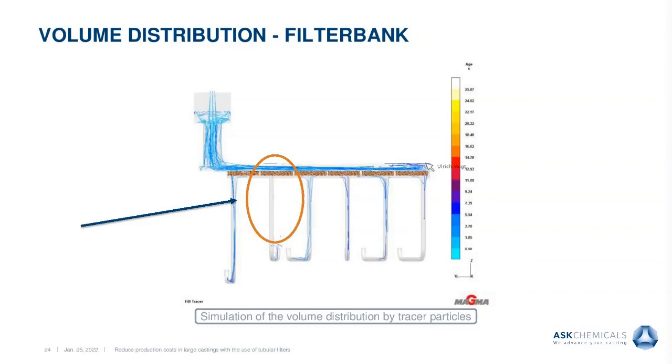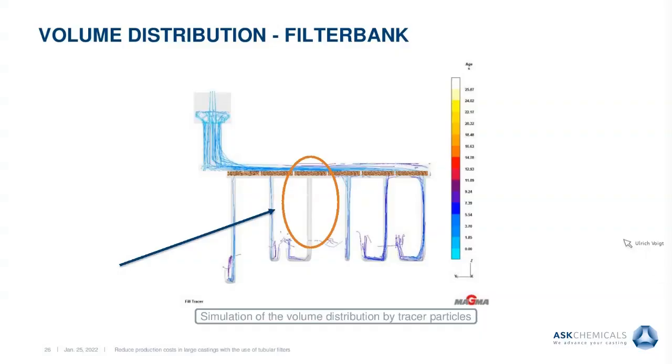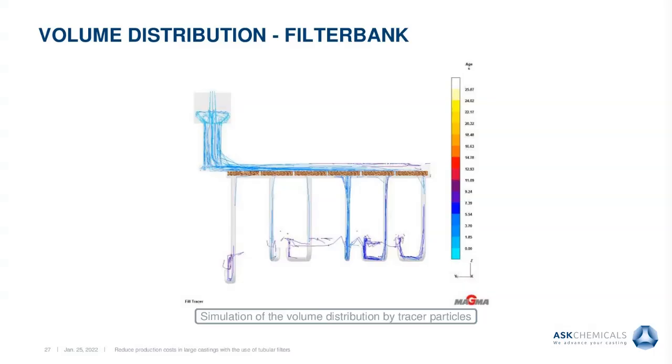And then you can see here the next slide. One ingate is no longer really filled. That means the risk of what I mentioned before, air entrainment, is also very high here. And you can see the next one is not completely filled either. And so it goes like a red thread through the complete process until this system is completely filled.